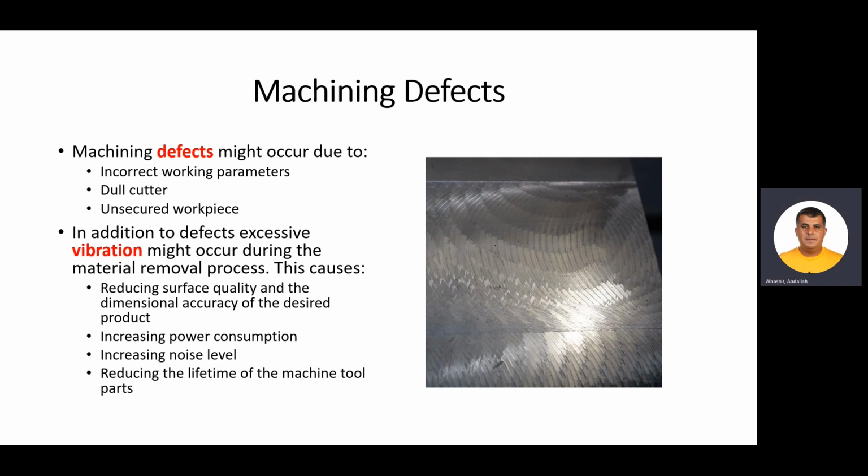And in this case, we say that this is a defective surface. The causes of the defects are incorrect working parameters, or a dull cutter, or an unsecured workpiece.